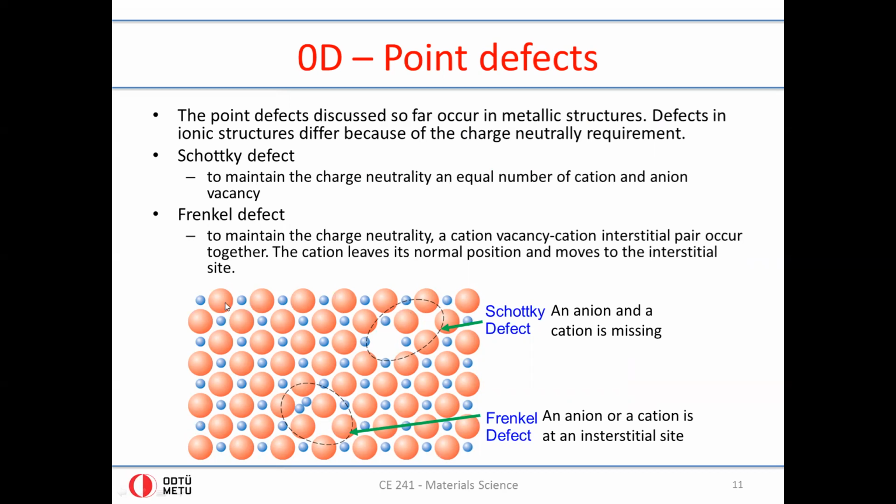And you may imagine that if you have a vacancy, as shown here, which is in an ionic structure, referred to with this special proper name of Schottky defect, not only one atom is missing, but two ions are missing because one is positively charged. And for electrical neutrality, you need 1 plus and 1 negative to be missing.